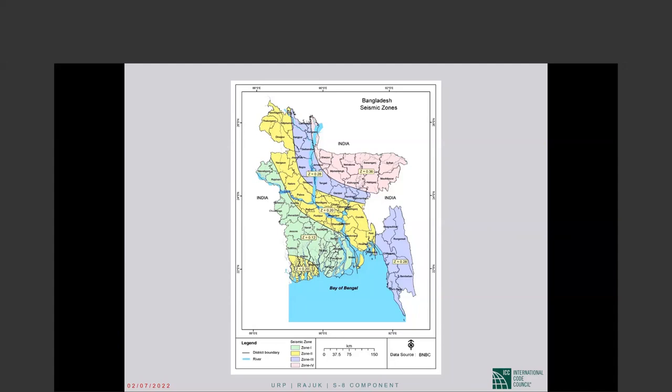Basically, you can increase the stiffness of the building by putting shear walls in wherever there is scope, or you can try to make those columns very ductile after the fact, which is a very expensive solution. There are other innovative things you can do, but there are only expensive solutions. So the owner has to be willing to spend the money and engage the right help, and even then it is not going to be easy.